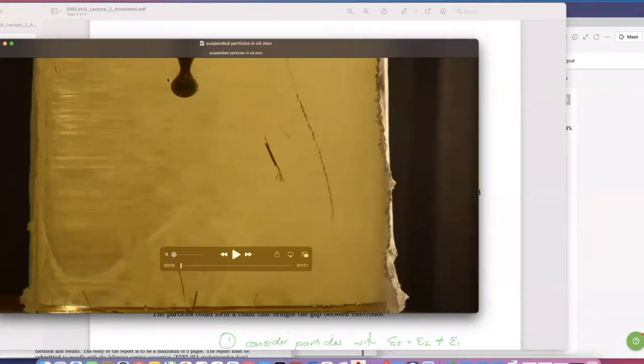So at the top here, there's a high voltage electrode. At the bottom here, there's a ground plane. So that would be at 0 volts, and that would be at a high voltage. This is transformer oil. It's in a yellow color. And those particles there are just grass particles. Your electric field will be very high around the electrode and not as high around the ground plane. It must be noted that those are not really conducting particles. It's dried grass. It's just a dielectric with a permittivity.